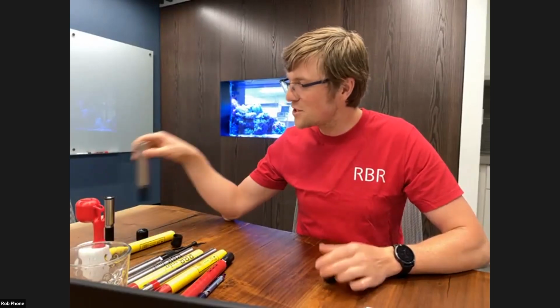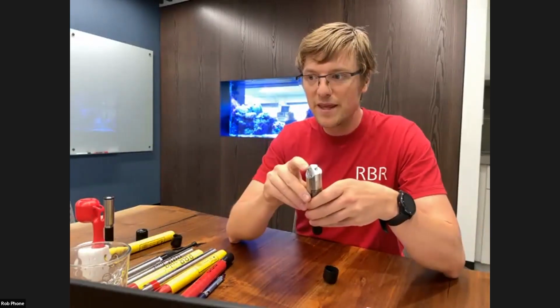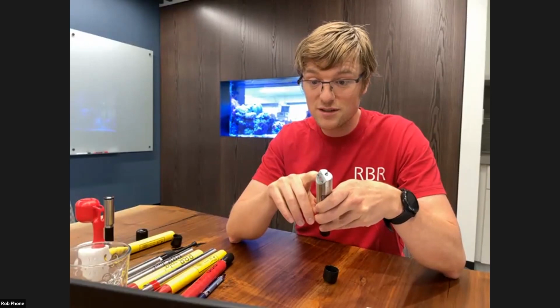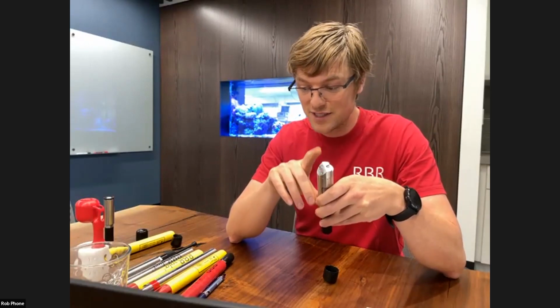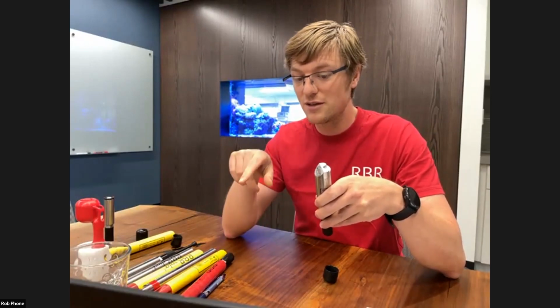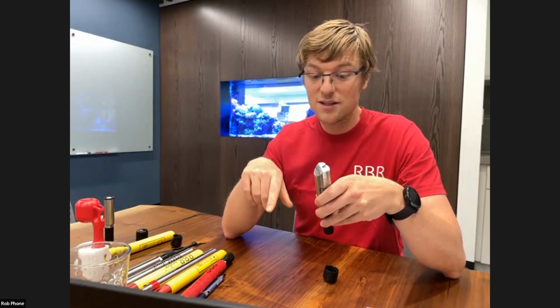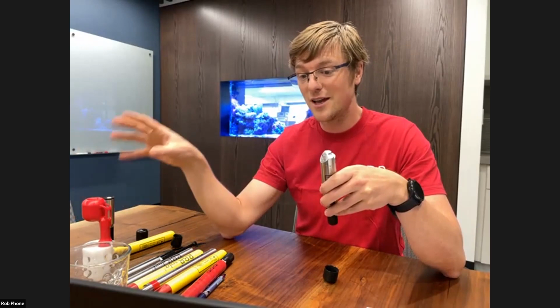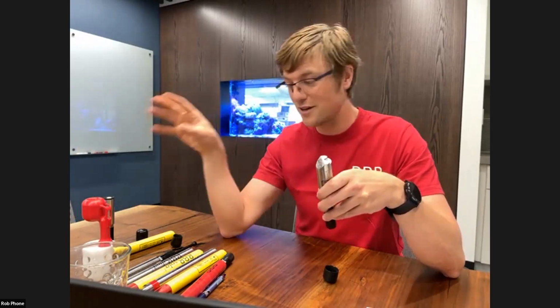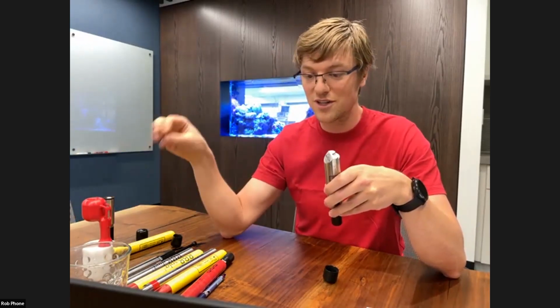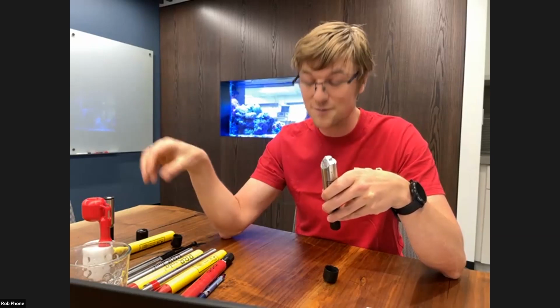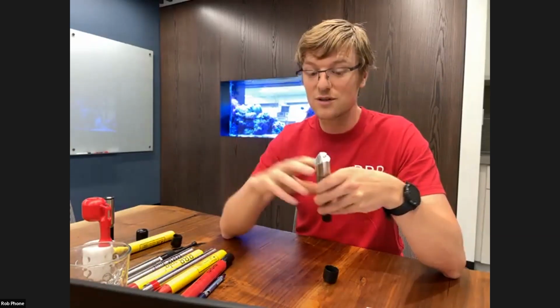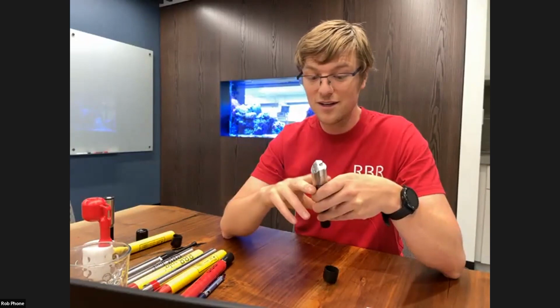The oxygen optode, so the measurement of saturation is independent of salinity, but concentration is dependent on salinity. So just like the pressure, if you have a conductivity sensor and are measuring salinity and you integrate an optode onto a logger that also has a salinity sensor, it will do the compensation there.